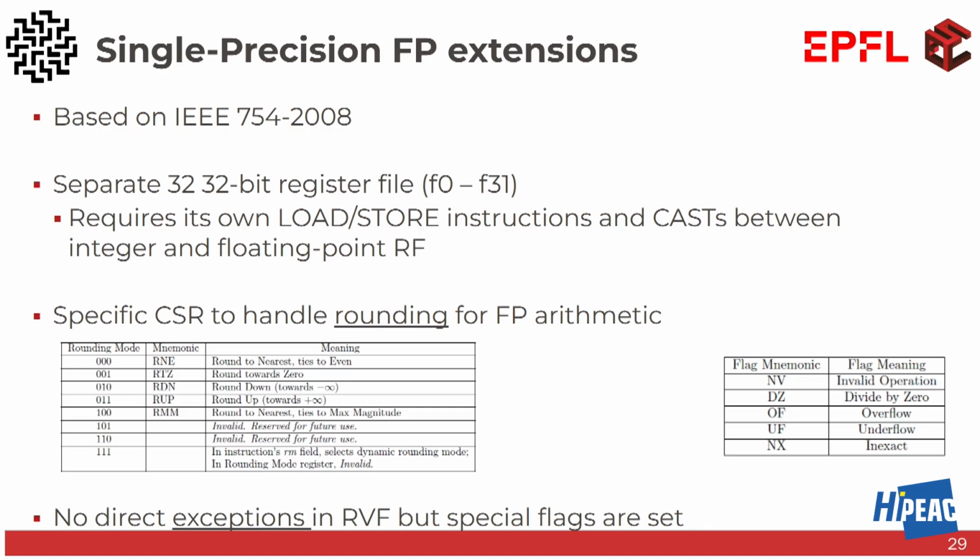How will you guys implement the floating point load and store? How will you move it there? You can copy it from the register file of the integers to the register file of the floats. Okay, so every time you load a number from the memory, you need 2 instructions. One, you load, and then you move. Right? I want to be like philosophically RISC, yes. Philosophically RISC, yes, okay. Then, otherwise?